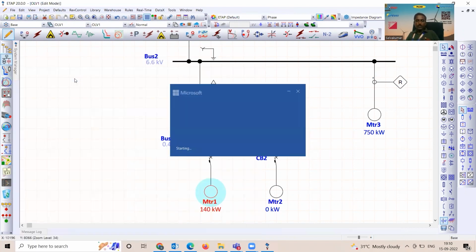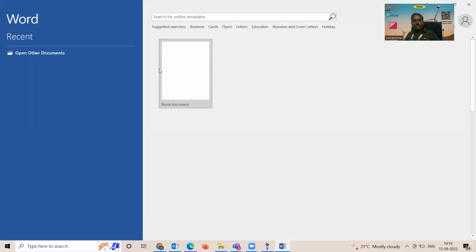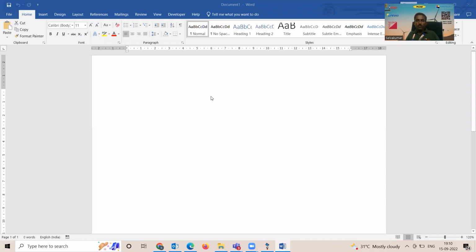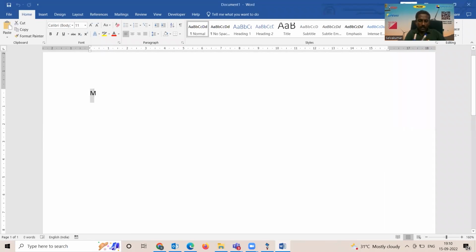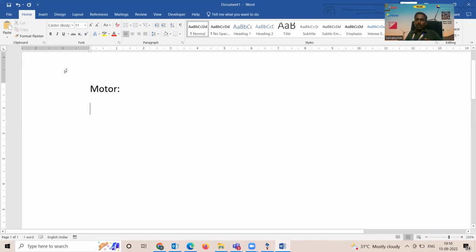When we are talking about motor protection, what is the specific information which we need to ask for? I am trying to protect the motor with overcurrent and earth fault. In order to set overcurrent and earth fault, what information do I need from the motor? I'm not really asking about the network, I'm asking about the motor. What information do we need to ask for a motor to protect that motor? Of course, a data sheet. In the data sheet, more specifically, what parameters?